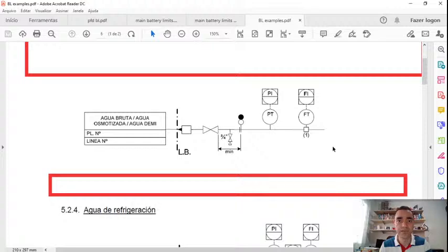And that is very important when we are talking about flammable fluids and when we are talking about toxic and corrosive fluids. So in some cases it is very important to consider this kind of fitting, because you just need to turn around the fitting and we have the isolation of our battery limit.